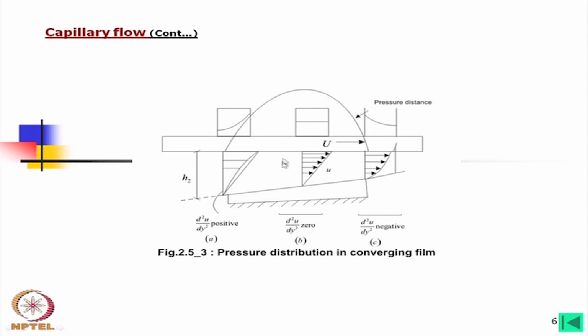So, with this pressure, the plate will float, and obviously, if there is no load, the gap will try to increase. If we put a load here, the magnitude of this load will depend on how much pressure is being developed here. Definitely, the magnitude of this gap has a role.